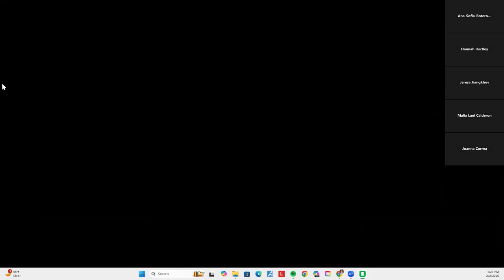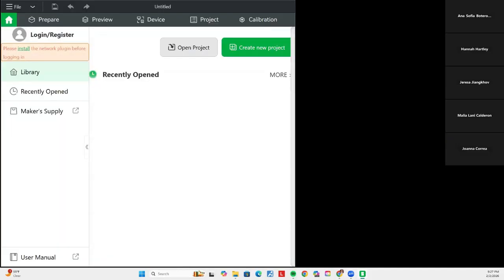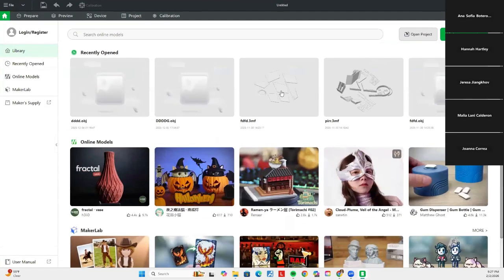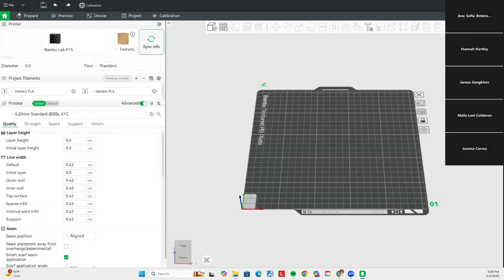My software, Bambu Lab, is very good at detecting what they call manifold edges, or stuff that's not closed. That's super good. But sometimes no matter how open or how closed it is, it will still detect it and won't work. So it's important to make sure it's closed and set to the zero plane.